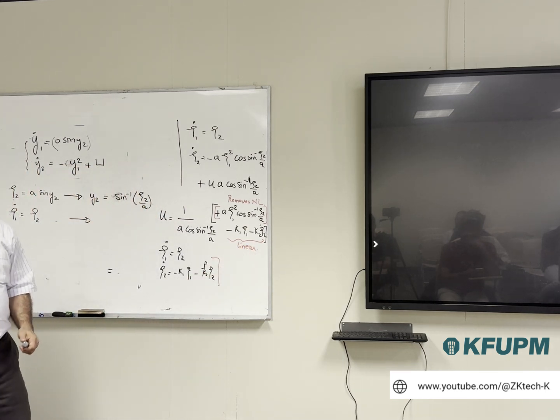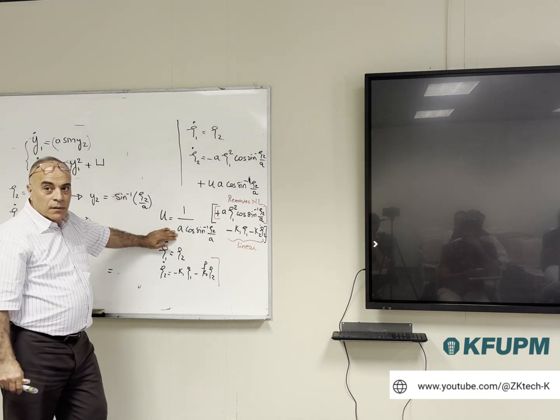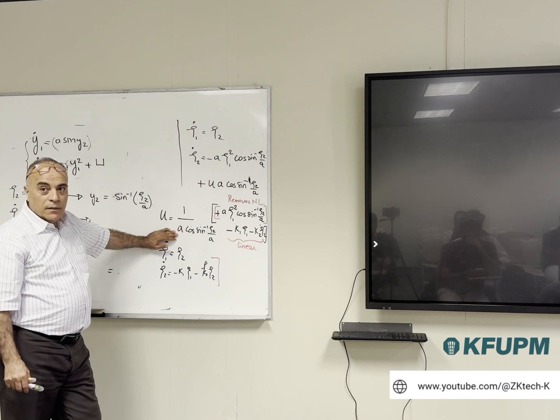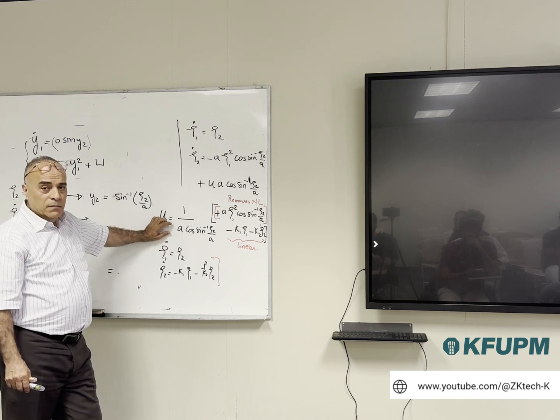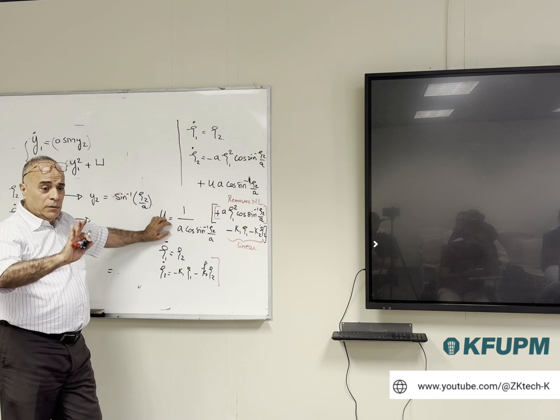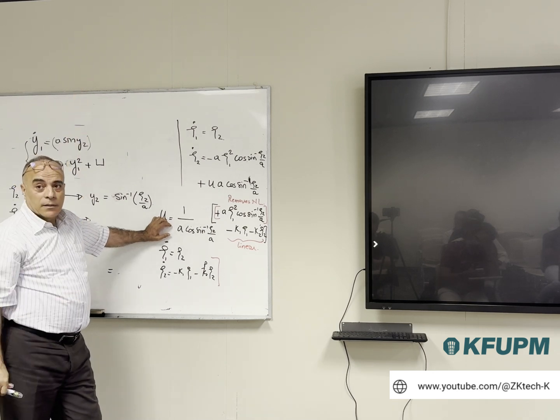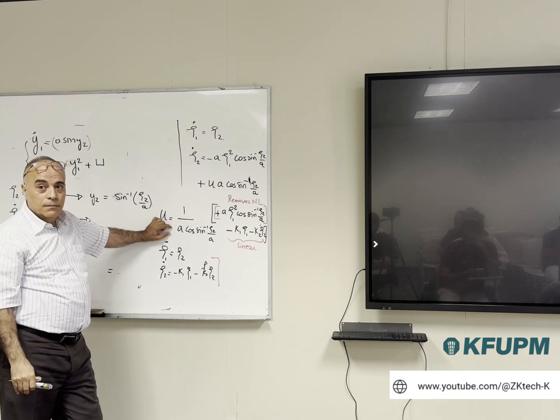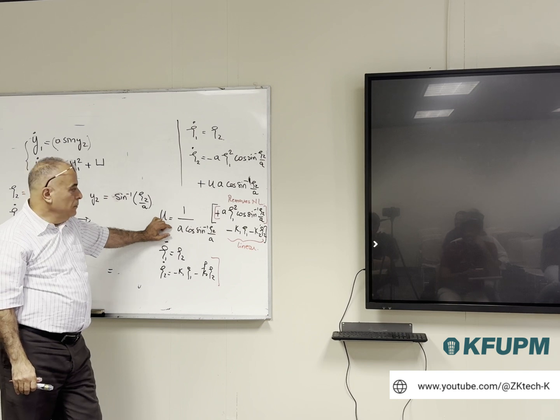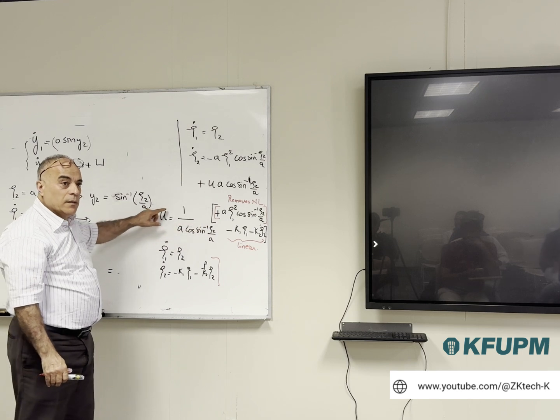I have a question. Yeah. Why, when cos goes to 0, is that a problem? Because you are dividing by cos, with 1 over cos. Yeah, it will go to infinity. So, for example, if this is your drone, you don't want your drone to be taken off like this, at pi over 2. So the system here is not defined everywhere.